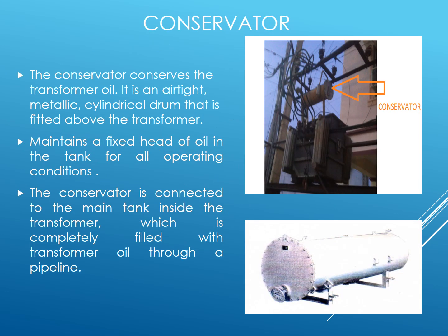Conservator. The conservator is an airtight drum mounted on the top of the tank. As I said earlier, when the transformer starts working, there will be a loss in the core as well as in the winding. Due to that, the temperature of the transformer oil increases.